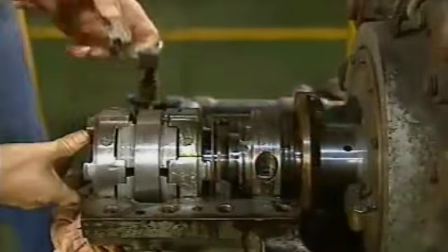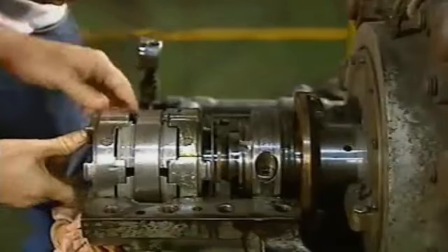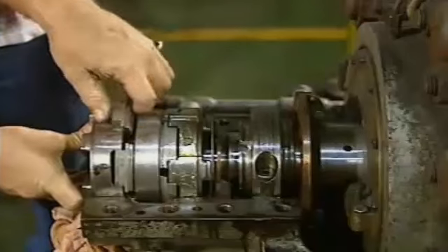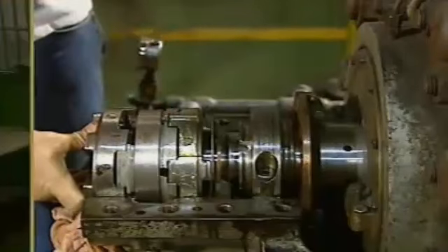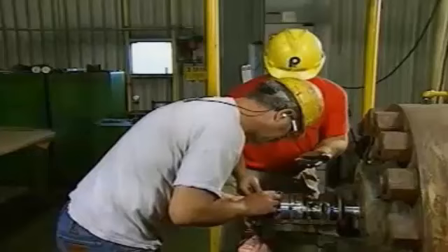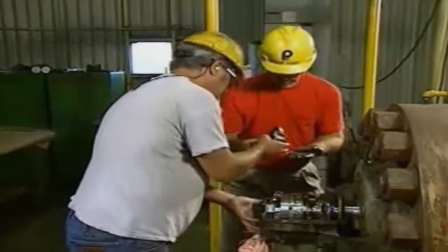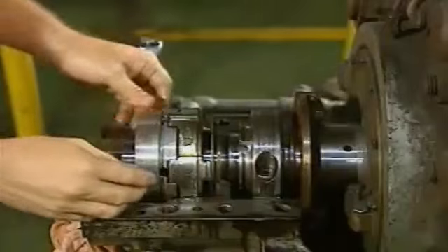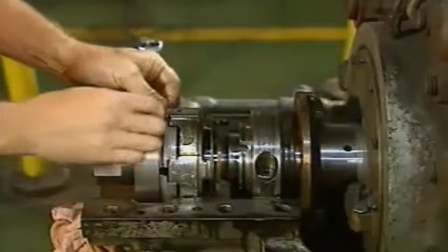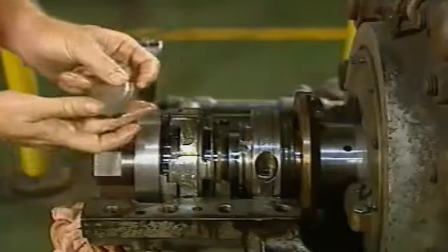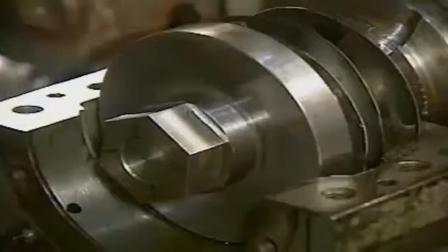The mechanic begins by removing the thrust shoes. The thrust shoes are placed on a clean work surface to prevent them from collecting dirt. Then the support brackets are removed. They are also placed on a clean work surface. Once the outboard thrust bearing is completely removed, the process is repeated to remove the inboard thrust bearing. After both thrust bearings are removed, the next step is to inspect the thrust collar.